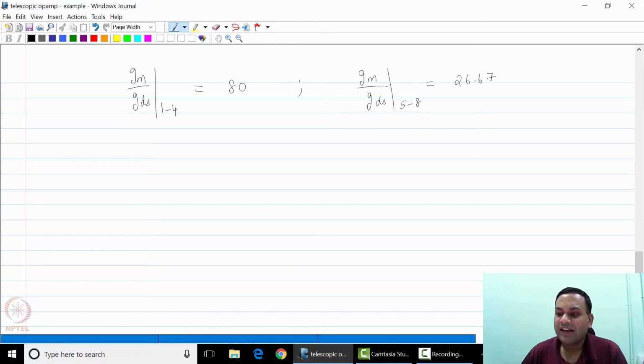This is because we have apportioned higher VGS minus VT for the PMOS transistors, which means they should have a smaller size, and for the same current they will have a smaller GM. And because the lambda of the PMOS is larger than the lambda of the NMOS, it turns out that the GDSs are larger for the same bias current and the RDS is smaller. Therefore, for this particular set of device parameters and the particular design we are looking at, the intrinsic gain of the NMOS transistor is much larger than that of the PMOS transistor.